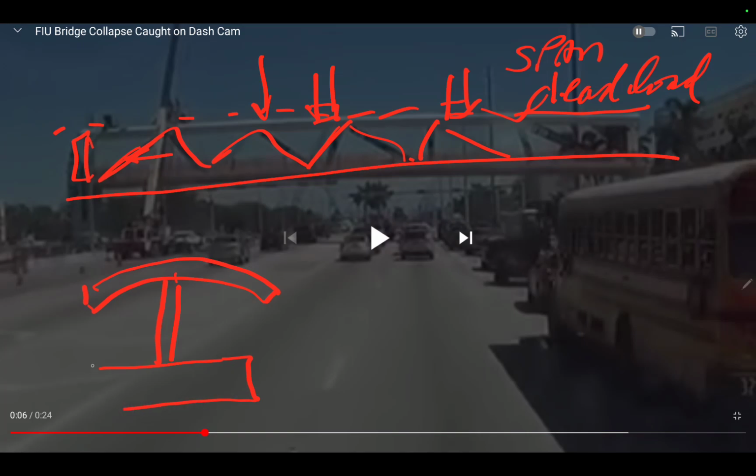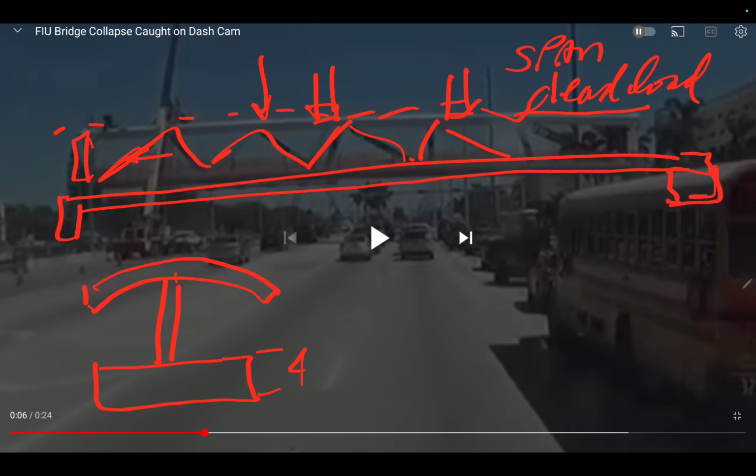So it's just a canopy. This is the diaphragm. It's huge, it's like 4 foot tall here at the end. Right here, 4 foot. Not the column. This is the deck now. These are huge, different dimensions on that end. On this end, it's approximately 4 feet, and they use post-tensioning here, down here, to hold the structure together. And they had some post-tensioning up here too to keep the canopy from flapping over. And this is the side profile of it. It's like an I-beam is what the engineer's intent was talking about.